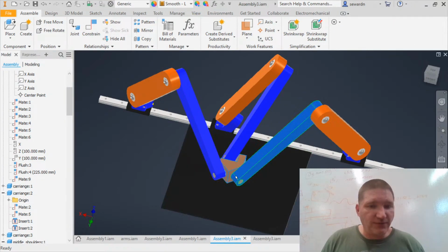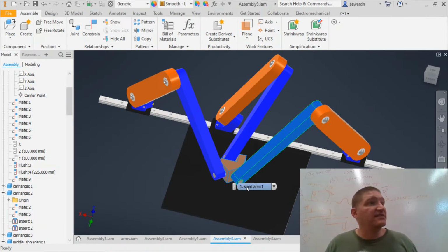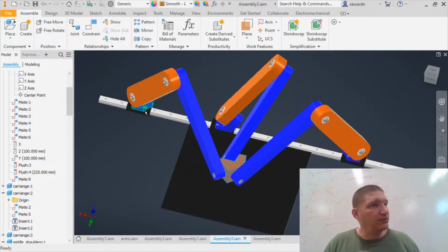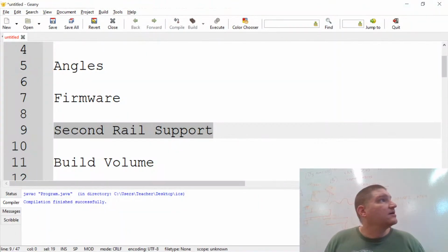And I'm not going to put that much force on it, because I know that this is a squishy robot. The end is going to be defined by these long arms, and the rigidity drops off the longer you get. So I'm going to try my hardest to keep the weight down. It's not the carriages that need to be held nice and rigid. I'm not going to have torque problems. It's the arm rigidity that's going to be the main problem. So those arms need to get beefed up. If anything, the rail is way over engineered for what I need.